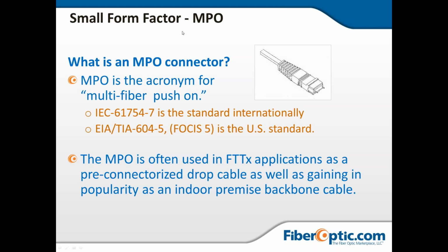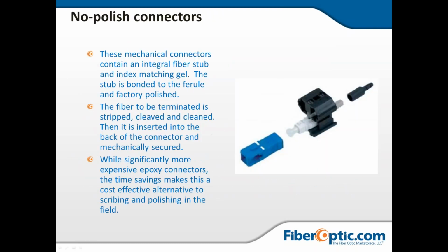What is an MPO connector? The MPO is the acronym for multi-fiber push-on. The IEC and the EIA, TIA, this breaks down both internationally and for the US standard. The MPO is often used in FTTx applications as well as pre-connectorized drop cable and is gaining popularity as an indoor premise backbone. More commonly internationally, and it has a higher cost here in domestic.